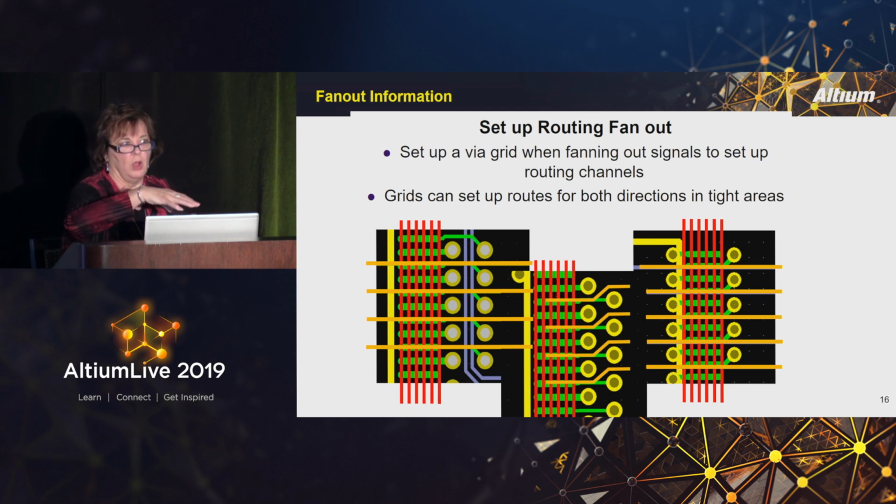So it's a reverse pad, if you will, but it's going to force an opening around the via in any plane that via is located in. So you don't want the signals to bump into the antipads around those holes either. So you want to set them up into a grid pattern such that the antipad opening is not affected by this trace going through here or this one here or this one here.